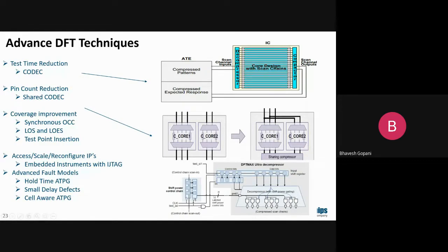At a time, based on this value, I can say a group of 3 is there. If I set certain parameters during ATPG, the tool will understand those commands and fill out those bits in such a way that it enables or disables specific chains. If only 3 chains are enabled, I can save the power of the remaining chains during shift.